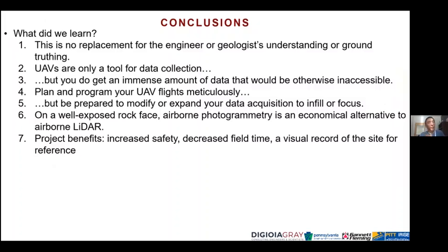So in conclusion, what did we learn? That there is no replacement for the engineer geologist understanding or ground truthing, and the UAV is only a tool for data collection, but it's a very important and powerful tool. You get an immense amount of data that would be otherwise inaccessible. And you must plan and program your flights meticulously, but be prepared to modify or expand your data acquisition to infill. On a well-exposed rock face, photogrammetry is an economical alternative to airborne LiDAR.